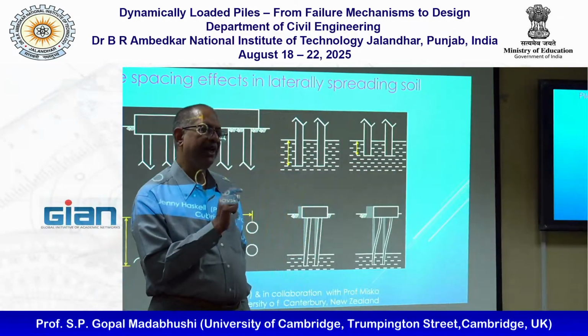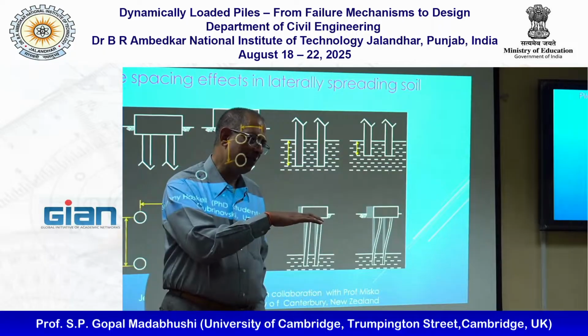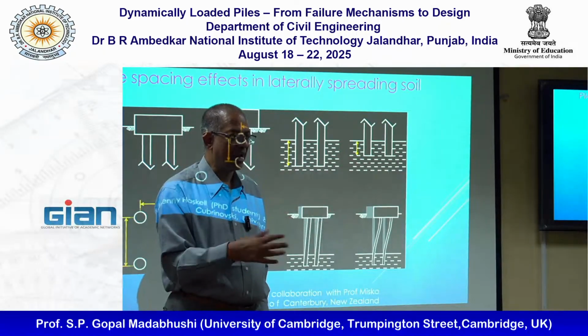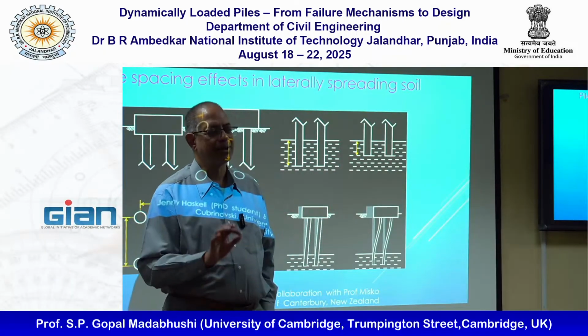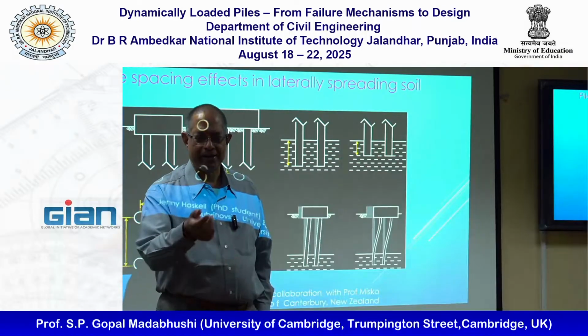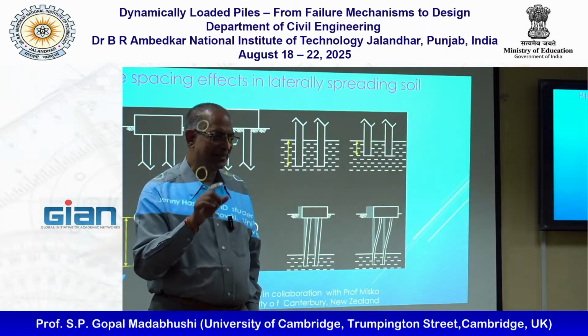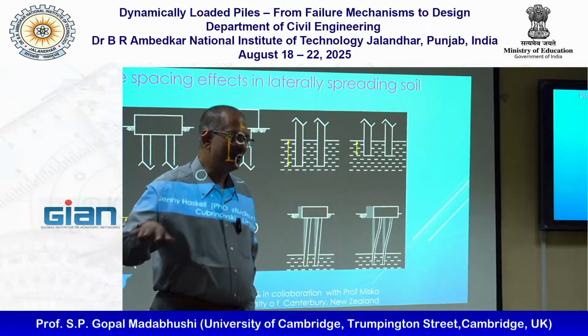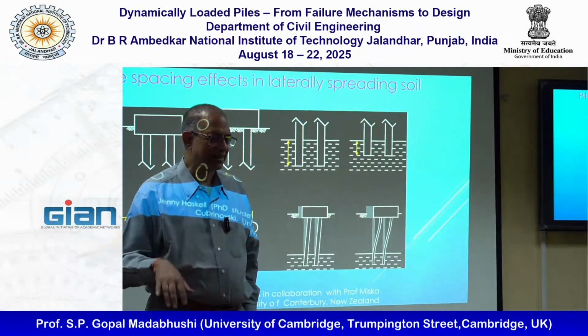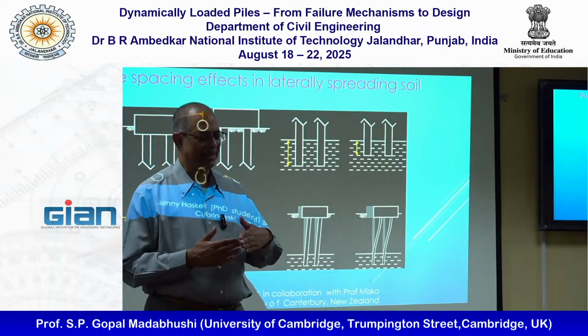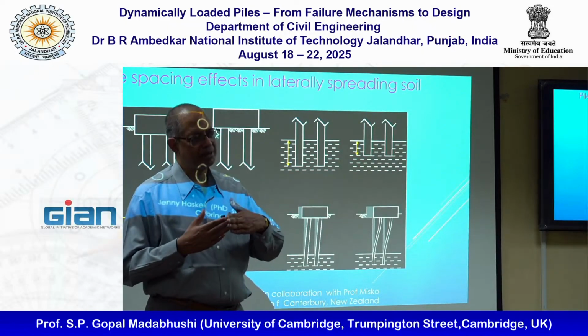The load sharing between the pile cap or the pile raft and the piles is a real interesting one. People like Randolph over years have come up with springs and pile as a spring, the beam on Winkler foundation type of analysis for the raft, and in the end there should be strain compatibility.